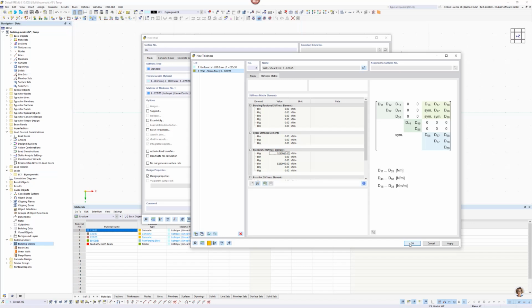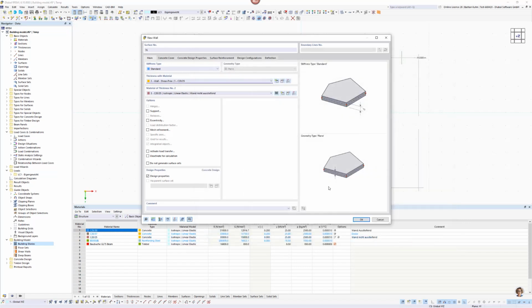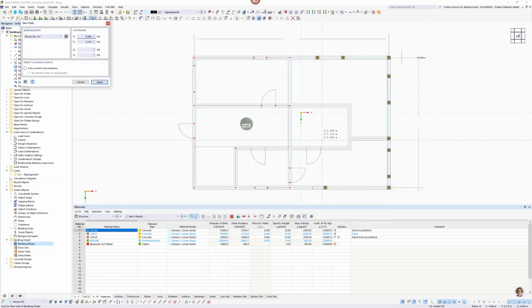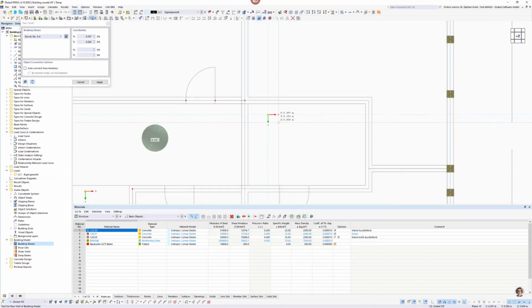So that's how the forces are transferred. There will be no bending stiffness or nearly no bending stiffness, which means in case there is force out of the plane, it will get a high deformation, but this can then be ignored. So it only transfers force from this edge to this edge.